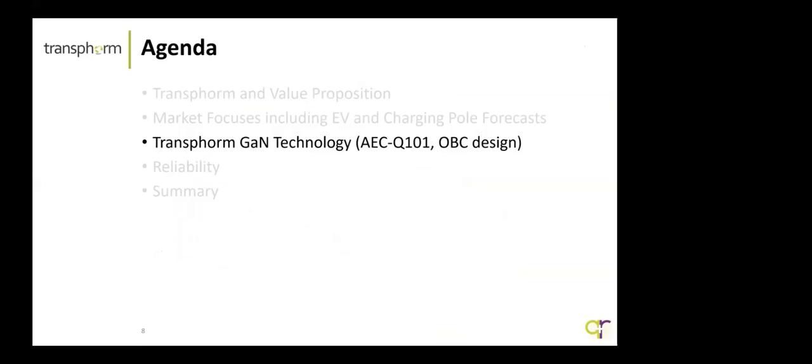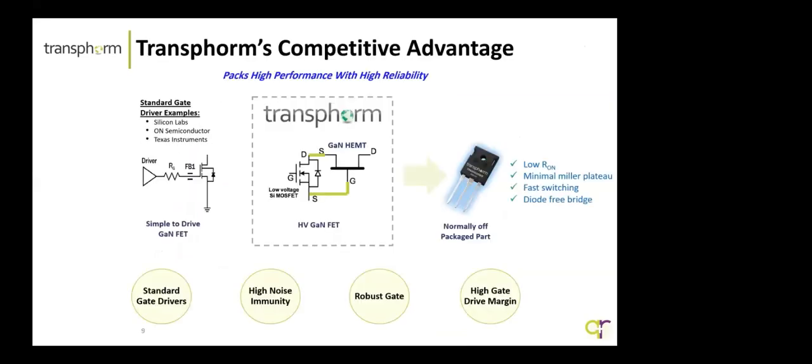So if we start looking at the GaN technology, the competitive advantage of our technology, as I stated earlier, is the ease of design-in, as well as drivability. Our technology, as you can see in the middle here, is a low voltage MOSFET that drives a high performance GaN HEMT D-mode device.